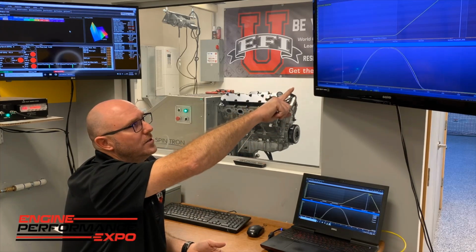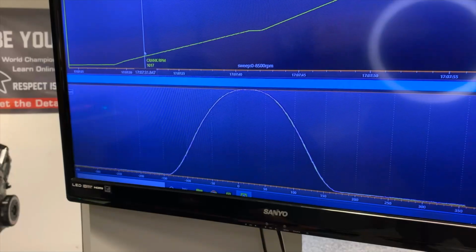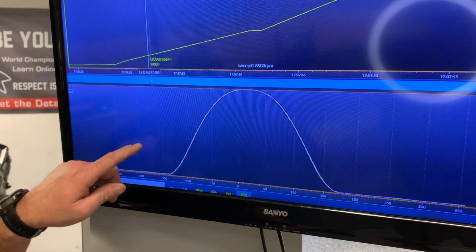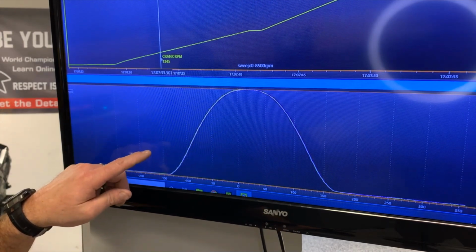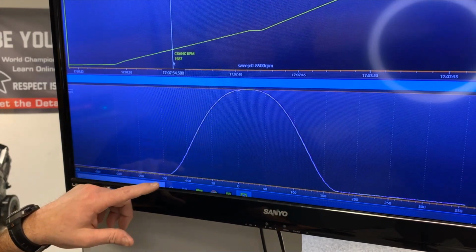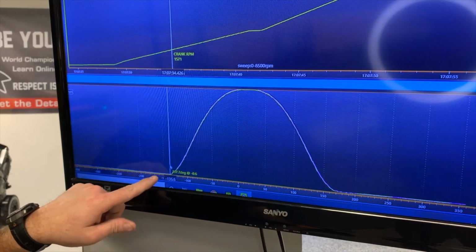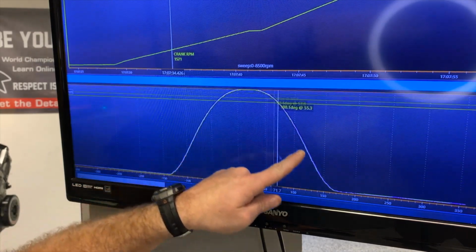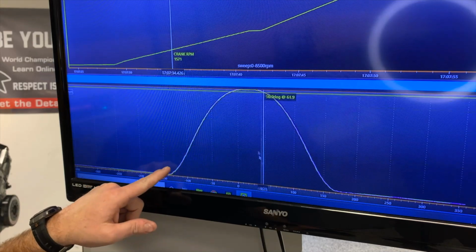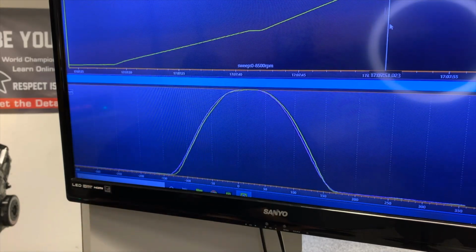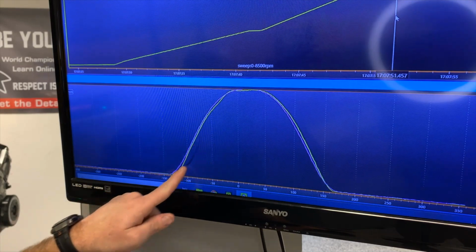Over the top here, you see that if we look in real close, there's actually a little bit of wiggle or bounce or whatever, and some of that can just be valve spring fluttering back and forth. The valve spring gets into kind of a surge state, and we'll get a little variable lift there. In severe cases, we'll even get like golden arches, like McDonald's, where it's actually bouncing the lifter off of the lobe of the camshaft. We don't like it when that happens.